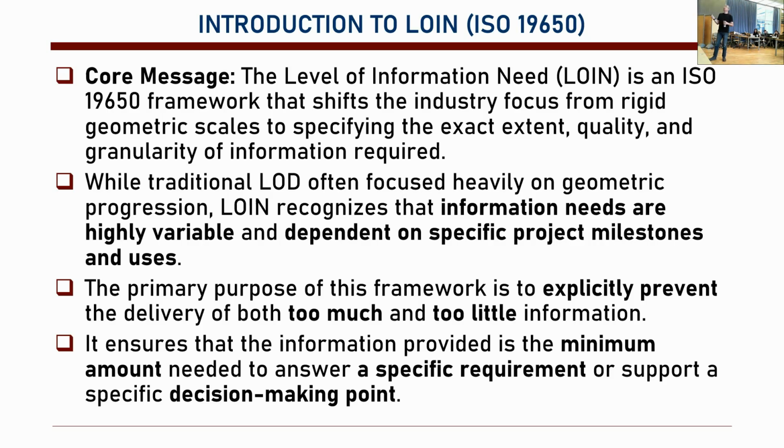Basically, we want to have the extent, quality, and granularity of information at any stage. We want to know what kind of information we need and why we need it. Okay? So LOD is focused on geometric progression. LOI basically recognizes that information needs are variable and they depend on different users. So we want to make sure that we don't have too little information or too much information. The correct amount of information. Okay? So what is the minimum amount needed to answer a specific requirement or support a specific decision-making point?